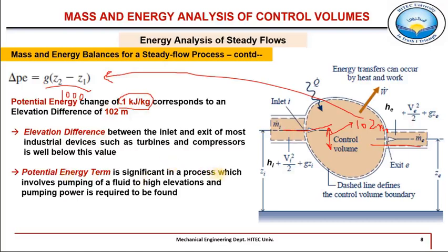So this term is significant in processes which involve pumping of a fluid to very high elevations, where pumping power is required to be calculated. If this height change is significant, then maybe this potential energy change is not negligible.